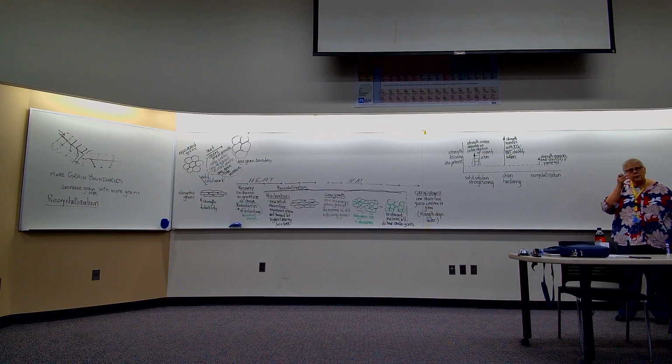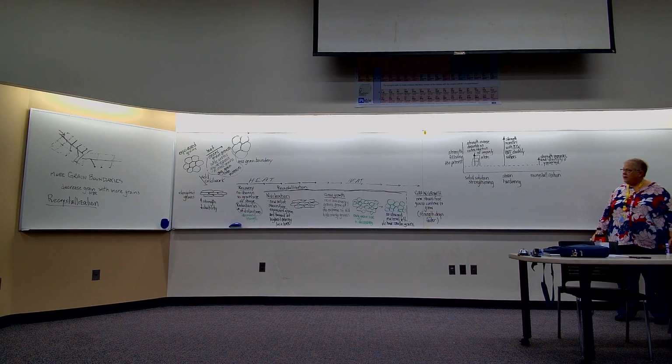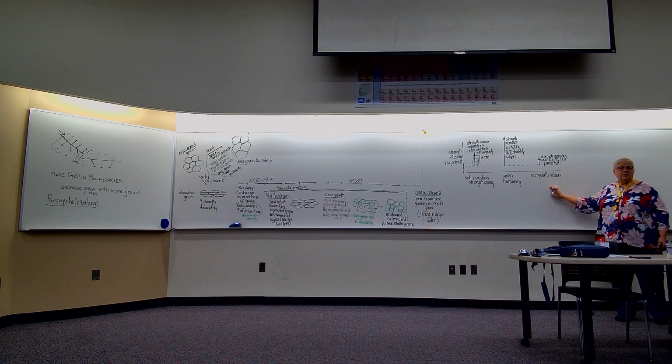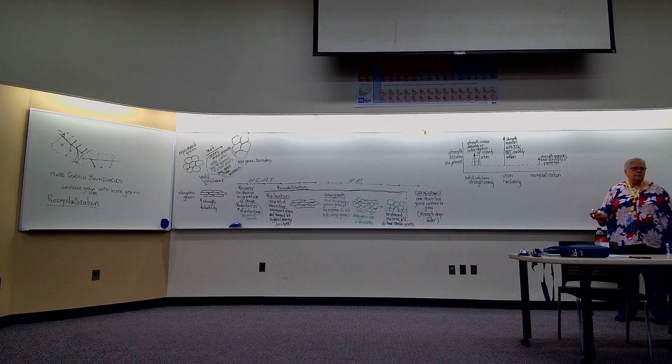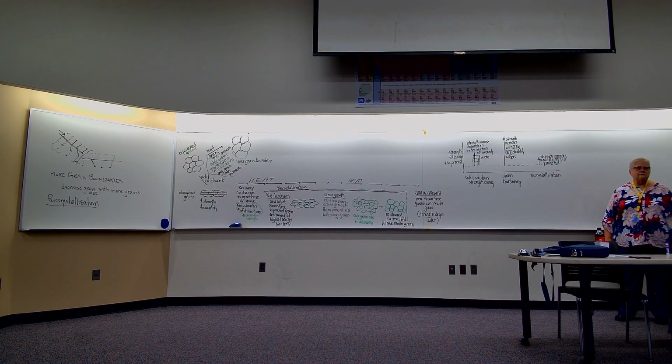Recrystallization, that's a time-consuming, heat-consuming method, but that's it. And I end up with a material that's ductile. So I might need to change the strength. Okay, I'm doing cold work anyway. I might need to change the size. I'm doing cold work anyway. But I can't have brittleness. Okay, well, we'll recrystallize after we do the cold work.